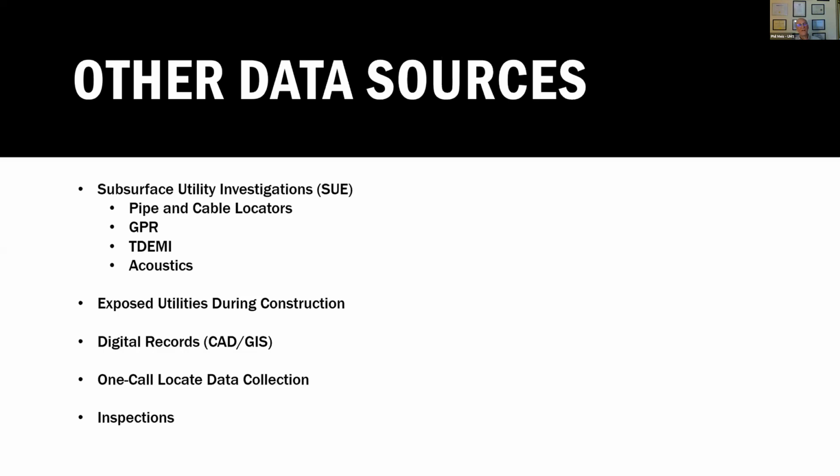I want to say the equipment is going to be developed. We've talked to Vermeer, and most of these trenching outfits have GPS hanging off them. It's just a matter of calculating the position of the cable with respect to the GPS receiver, getting the offset information. And as Eric said, all that attribute information is already inputted by the utility. So that data is all there. The rough alignment's there, and all the contractor needs to do is upgrade it with actual observations.